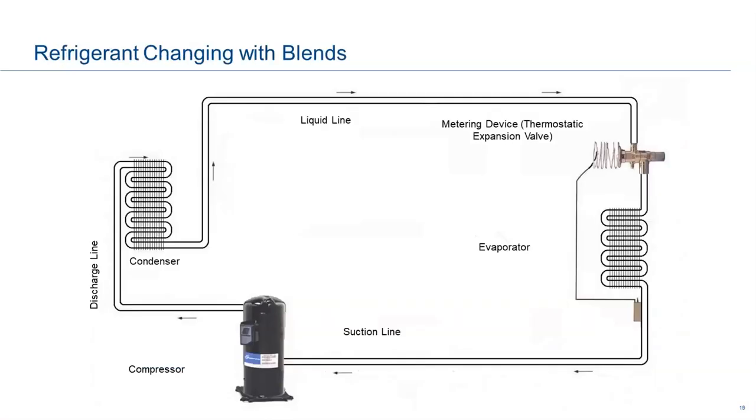So we're going to talk about refrigerant charging. We did everything we just talked about. We've got a system here. We haven't released the refrigerant yet. We brazed everything in. Our outside condenser, we're going to keep this very simple, is a basic air conditioner. So we have a service port here, a service port here, okay? We did our calculation on our line set, and by our calculation of the length of the line set, we're going to have to add another 4 pounds, we'll say, okay?